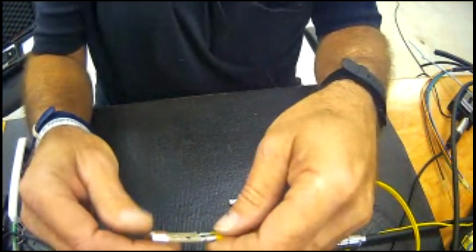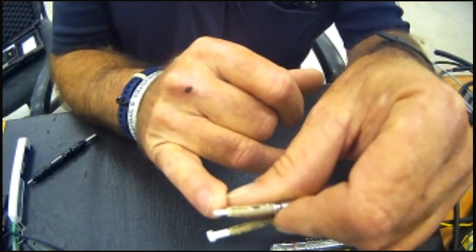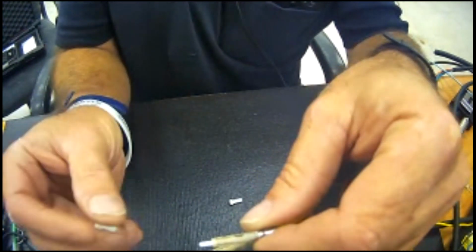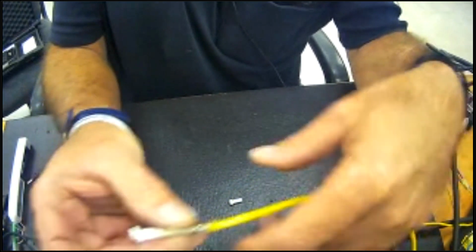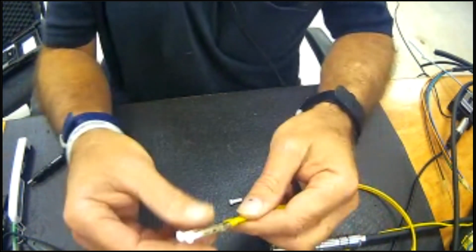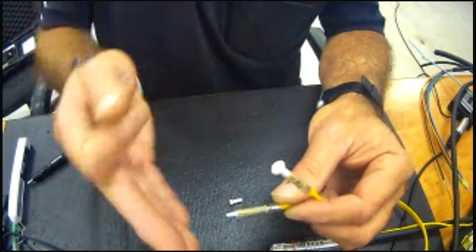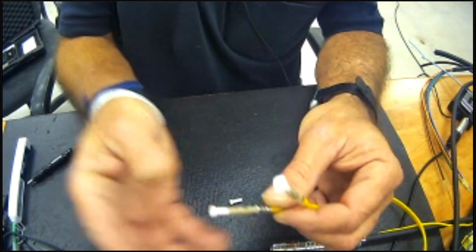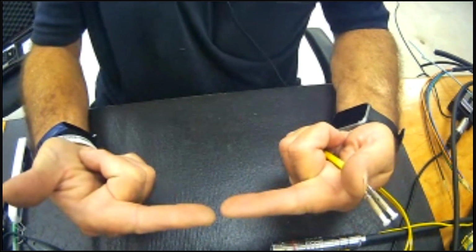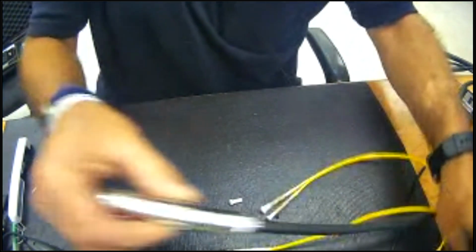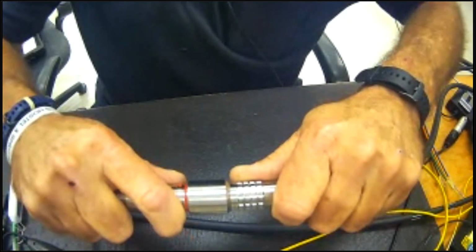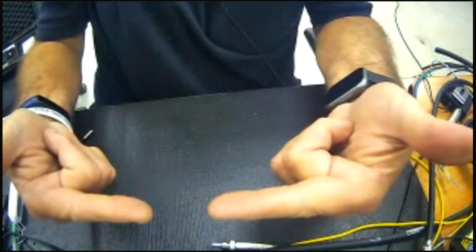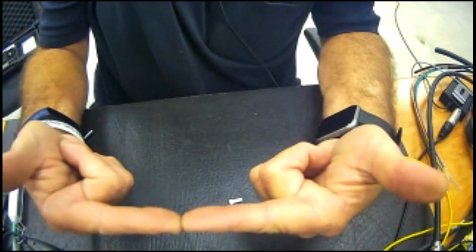The F2 contact, or SMPTE contact in the LEMO, is radius, very much like a ballpoint pen. Has curvature, heavily spring-loaded, and in order for us to verify that we're actually machine polishing it, besides testing performance, we actually need to verify that we're shaping the glass and shaping the zirconium to meet an industry standard. Why? Because there are 2 connectors that are jammed together. When I say jammed together, I mean they're jammed together. That's how we made these things. We jam them together. So inside, I have 2 fiber contacts that hopefully are clean that are getting jammed together.